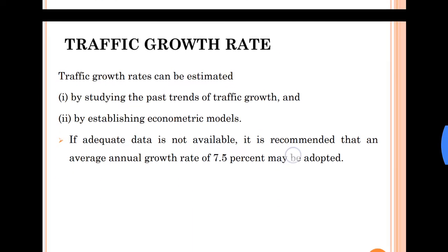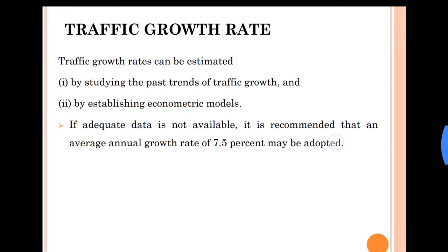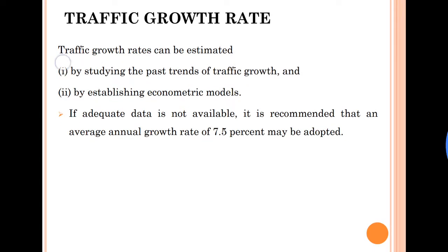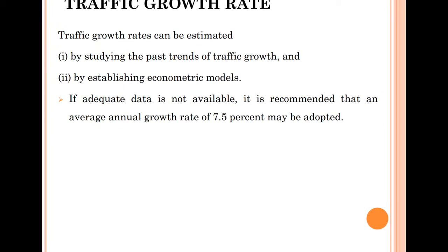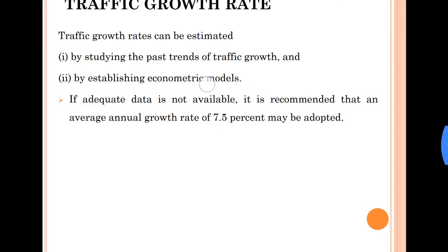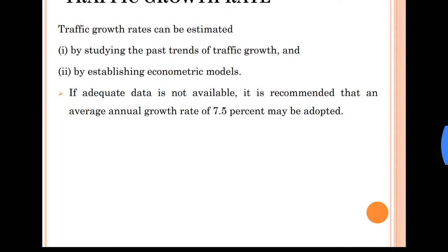Then we have traffic growth rate, as I already discussed. Traffic growth rates can be estimated. We need to estimate this part using statistics by studying the past trends of traffic growth. So we can study from the previous year to the upcoming next year what the growth in traffic was. Similarly, we can obtain a chart of previous years and their growth rates, by establishing econometric models, or we can model the growth rate.